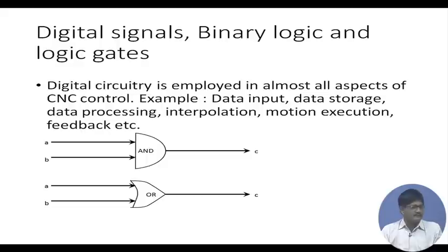In the figure we have shown two typical logic gates, and how do we read them? Like A and B, if there are two inputs which can only take up two values, like say high value and low value, AND gate is a gate which controls the relation of A and B in such a way that C is going to get a high value only if both A and B are simultaneously high. This is called AND gate. That means say x and y, if both are high, then only z is high,